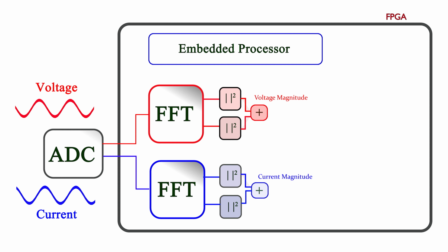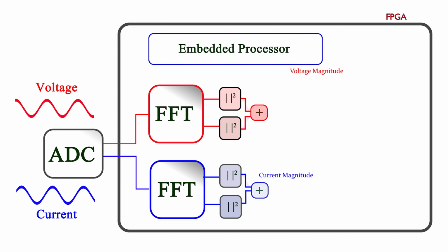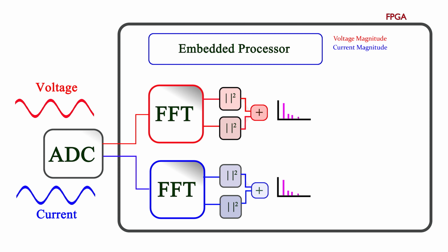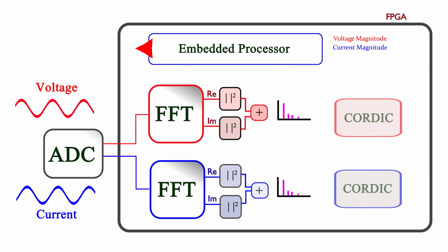So we're at a point now where we've established that the FFTs are working. We see that bin 10 has the 50 Hz fundamental, and bins 20, 30, 40 and so on have the harmonics of 100, 150, 200 Hz, etc.